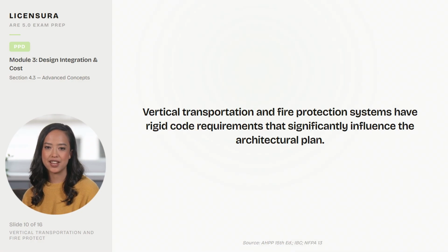Vertical transportation and fire protection systems have rigid code requirements that significantly influence the architectural plan. These systems must be integrated during DD because relocating them later requires extensive redesign.